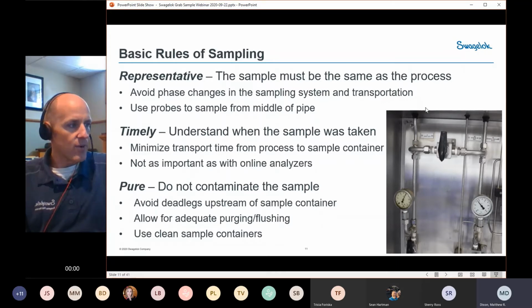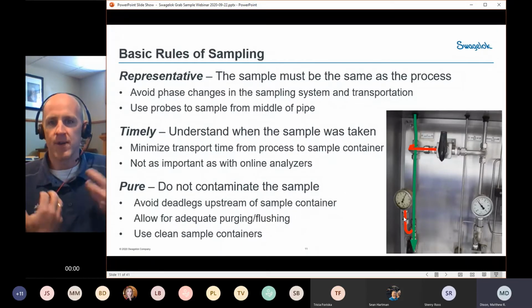So imagine you have your sampling system where we have a sample container that's off the screen down below here. And we have our sample flow coming in the top and flowing down. And notice we're flowing past 2 T's. We've got one T that has a gauge on it here, and we've got another T that goes to a bypass valve. Well, those 2 T's have these branches here in red that filled up with fluid at some point during the process. But how old is that fluid?